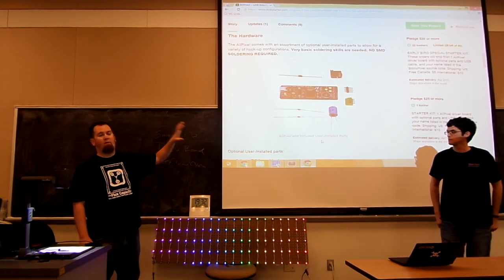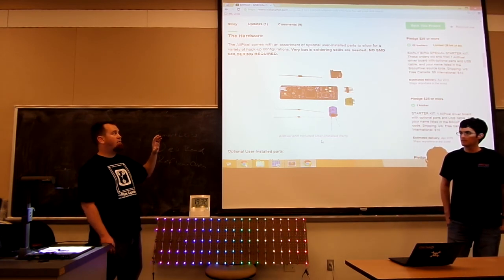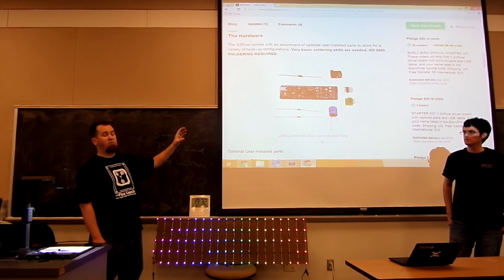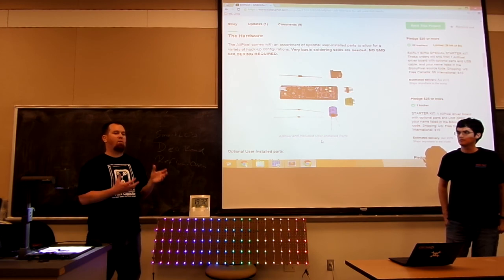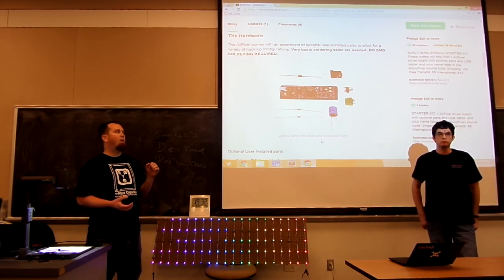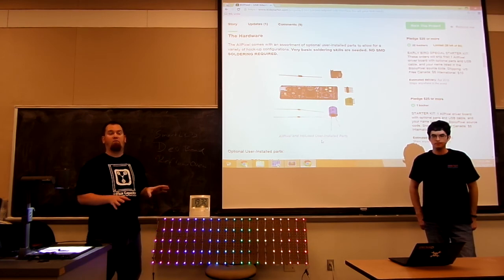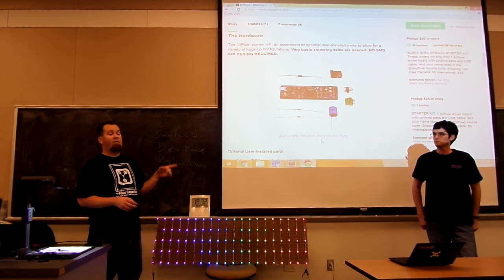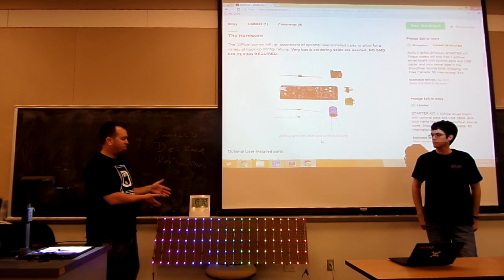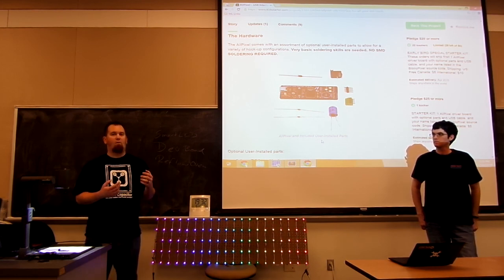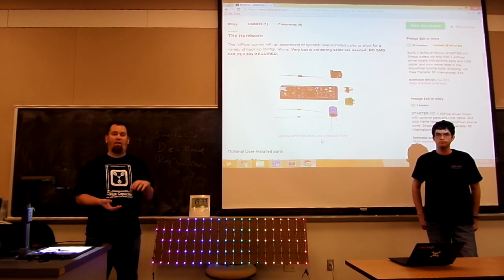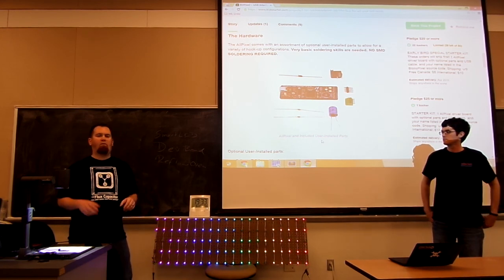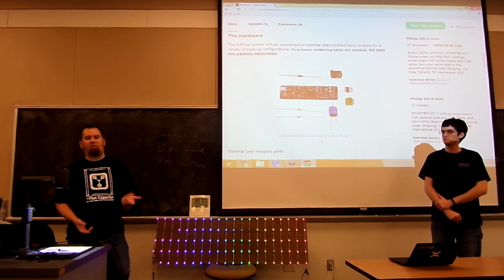There is an ICSP header on there. You can program it with that. If someone wanted to, for example, use this and just run animations directly off the chip, not using the Python library, they could go back to the old Arduino libraries, because at that point the USB serial speed doesn't matter. And then they could use a bootloader. It works fine, I have tried that. But the other reason I left the bootloader off is, as you noticed, when I change the strip type, it automatically reboots itself. If you leave the standard bootloader on there, there's about an 8-second delay, and that was just unacceptable for what I wanted to do. I wanted you to change it, and it goes, oh, it's a different number of pixels, different strip type, cool, reboot, back up. It's less than 3 seconds.